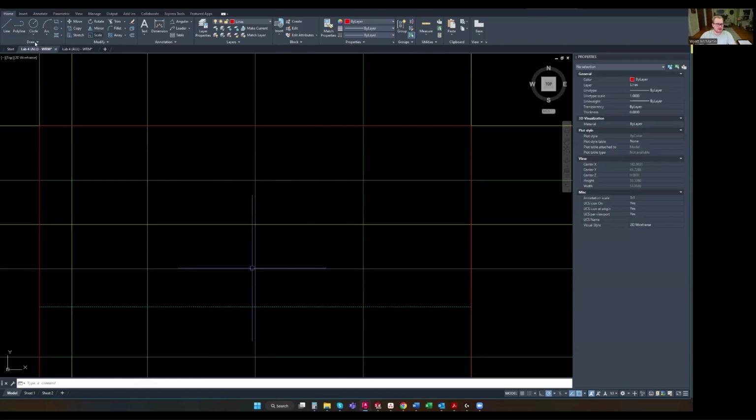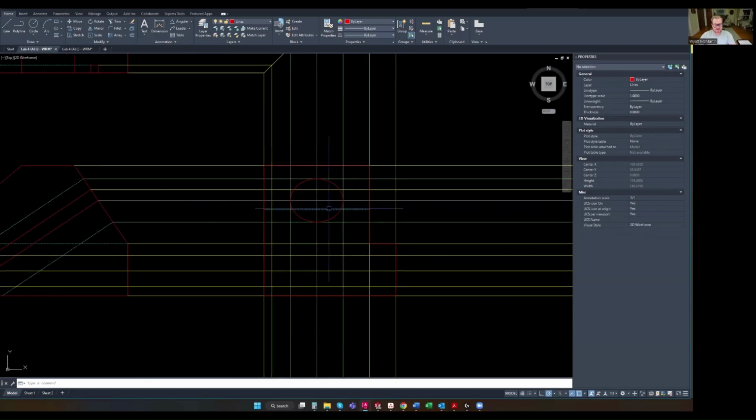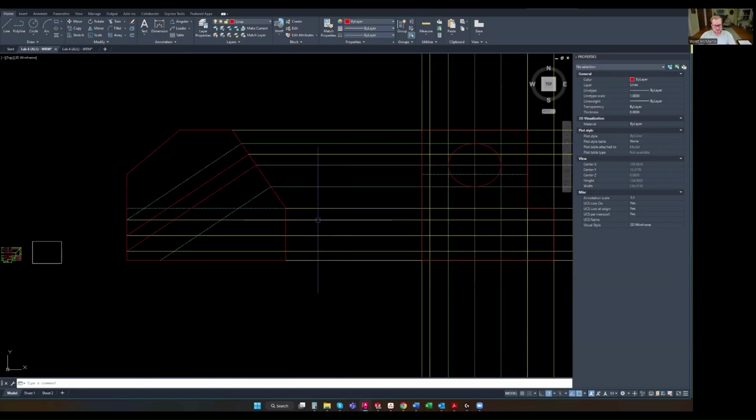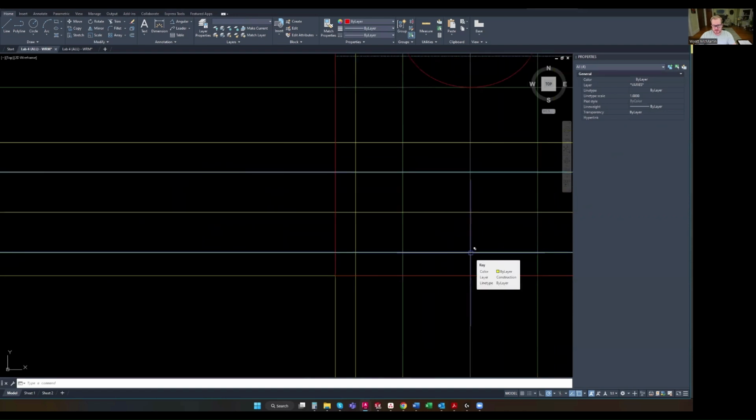So with that, let's go ahead. I'm just going to recreate my ellipse, grab my ellipse tool, start where the gray lines intersect, snap to the green, snap to the green, and now we can see and verify visually that we do in fact meet all the lines that we need to. And with that, let's go ahead and trace these lines out even further. So where this ellipse cuts through the bottom of the part is where this line is right here. The center line intersects with this line right here. So we know that our center point is going to be here. We're going to meet these green lines here. And then the other extent, the vertical extent, is going to be this line.